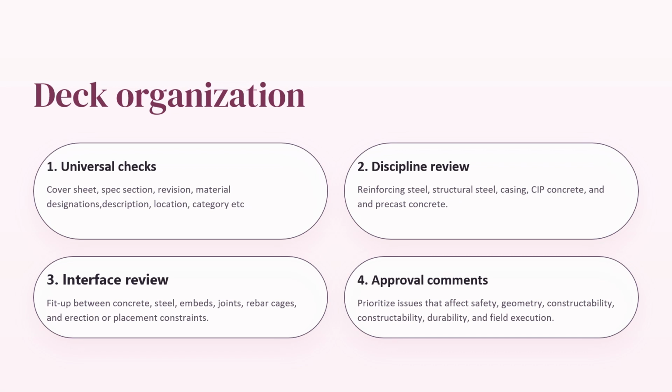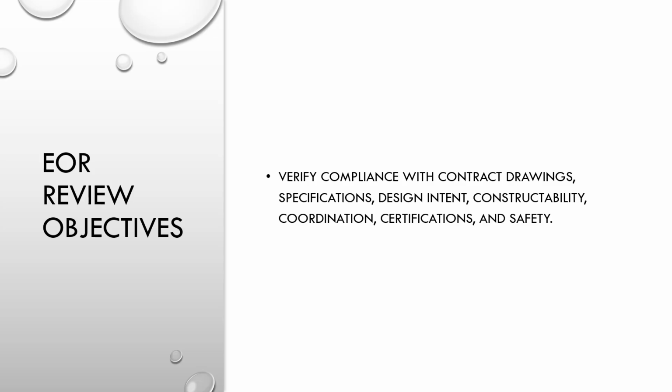And then after that, we check the interface review, which covers fit-up between concrete, steel, embeds, joints, rebar cases, and erection or placement constraints. The number 4 factor is approval comments: prioritize issues that affect safety, geometry, constructability, durability, and field execution. Let's go to another slide.